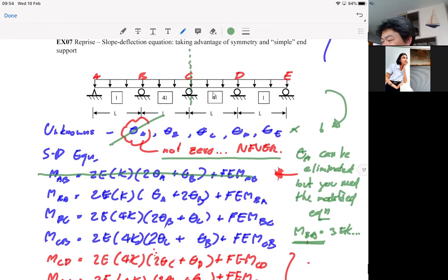So right here, the line of symmetry is here. So when you fold everything about the axis of symmetry, you have one picture that comes on top of each other perfectly. So that should be the case for the shear force and bending moment diagram as well, right? So for those of you who go that far and you see that the shear force diagram on the left and on the right are not the same, my, oh my, you should realize that. Okay? So I hope we are doing fine with this one.